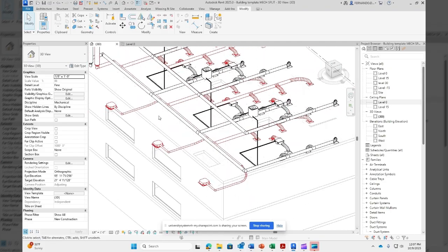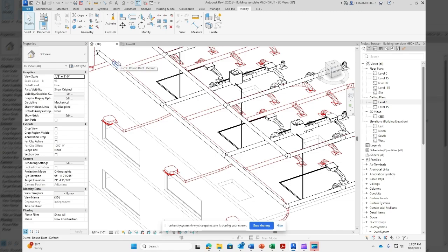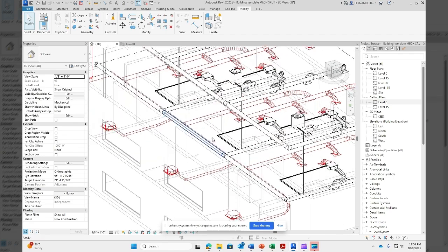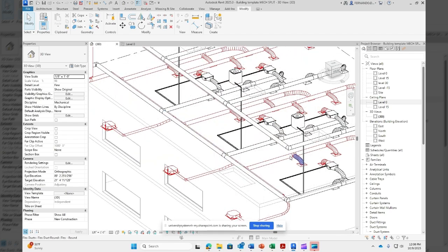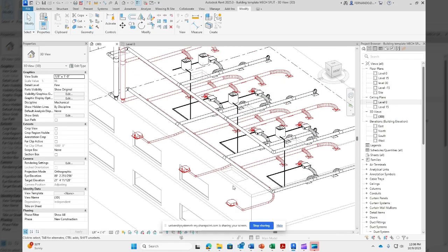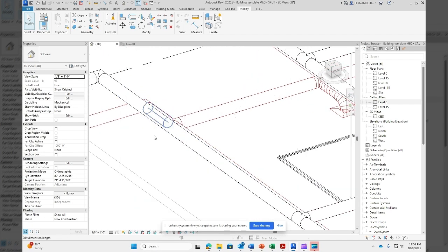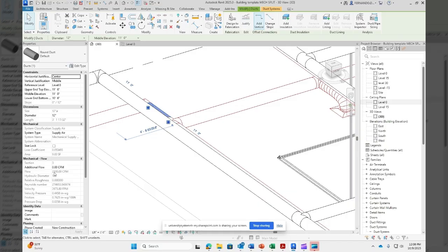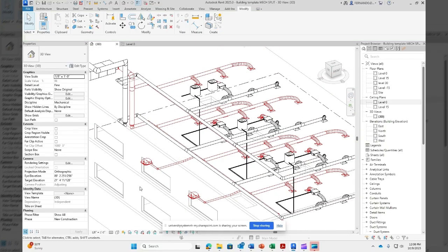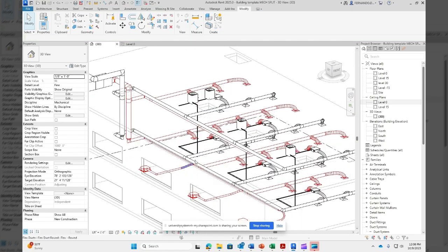If everything goes well, the final airflow at the end of the first floor must be 600 per classroom, so 1800, sorry, plus 1, 2, 3, so that would be 2100 if everything goes well. Yeah, 2100. What's next?